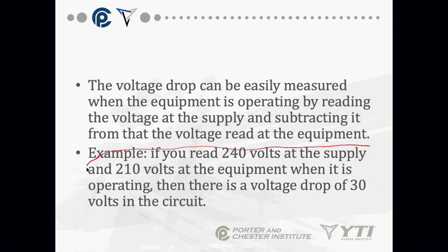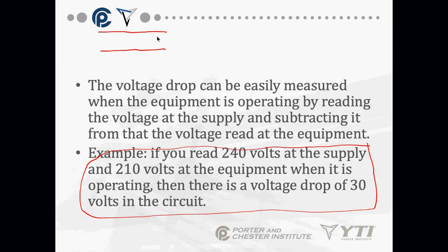But use a voltage monitor here. You put the voltage monitor right on the equipment. You don't put it at the breaker panel, you put it at the equipment, because, again, we need to find out if there's voltage drops along here. What happens if you have a 240-volt supply coming in from your breaker panel? It's going through a ceiling here, so I'm just going to put sort of dotted lines here. I come then into my disconnect, and then my equipment is over here. I'll just call it a box because it's something.